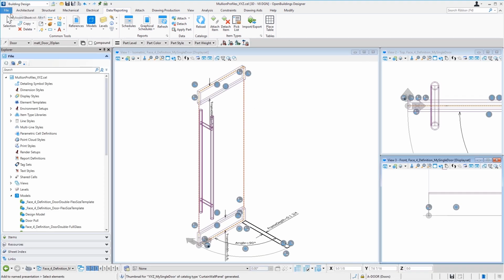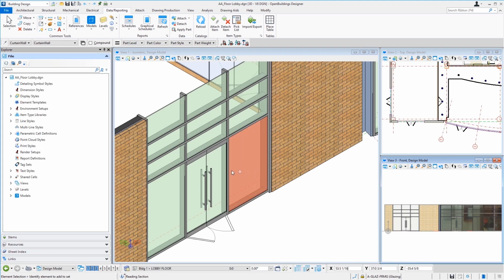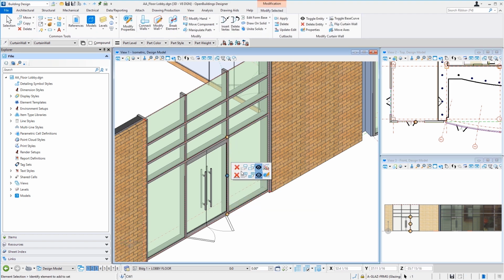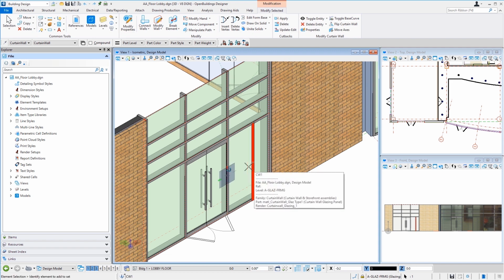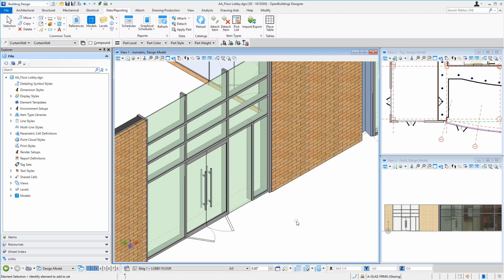So let's go back to our 3D model. We'll go ahead and place this in the model. So let's place a single door here. And I'm going to first copy this frame over 3 feet. And then I'll place the door in here in that panel. I'm going to first hide the bottom frame. I won't need that with a door in there.